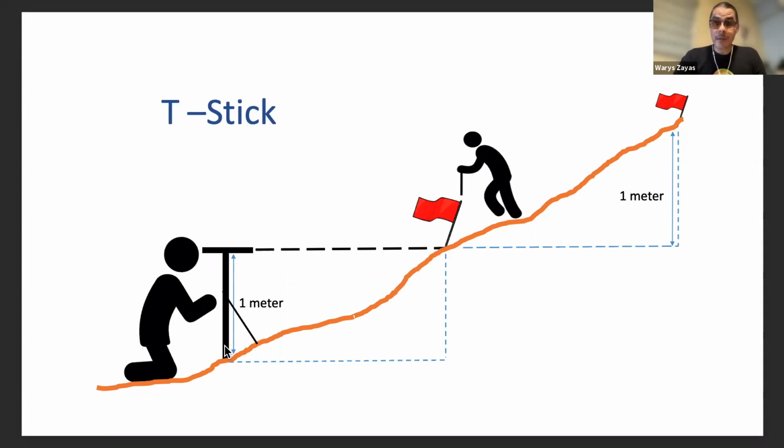On the other hand, if your slope is less than 15%, your disc or your boning rod height will be 0.75 meter, not 3 meters, right? So it's really useful. With 1 or 2 practices, you will learn how to use it, and it is really helpful, right?